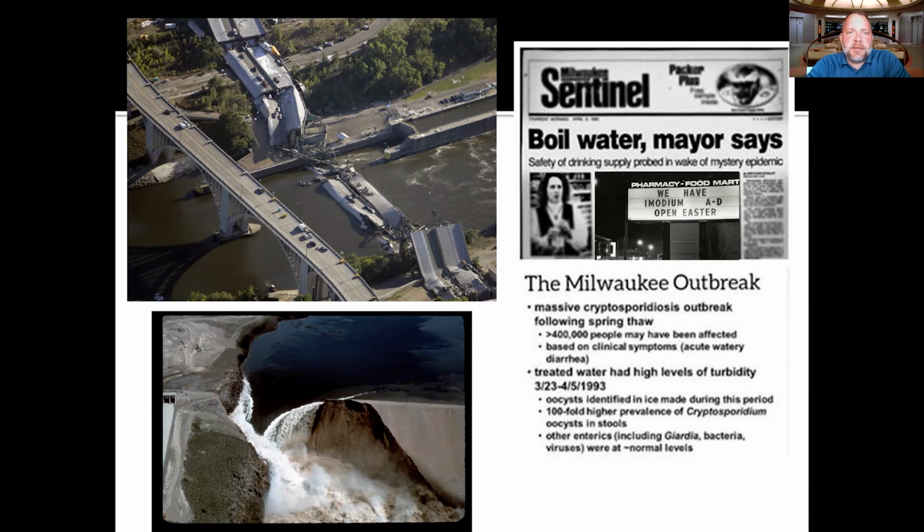If I'm remembering the numbers correctly, the engineer had specified 5/8-inch gusset plates for the steel girders under the bridge, and the contractor put in 1/2-inch gusset plates. And it lasted for somewhere around 50 to 60 years. But they were doing a deck rehab. They had some material stockpiled on the deck, which added to the static, or dead load, of the structure.